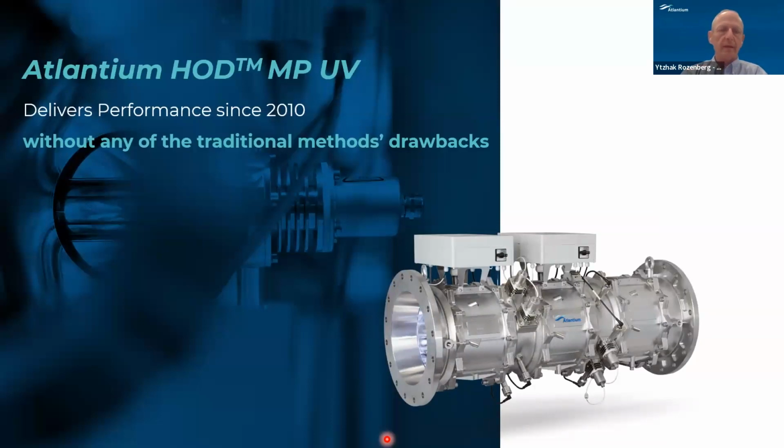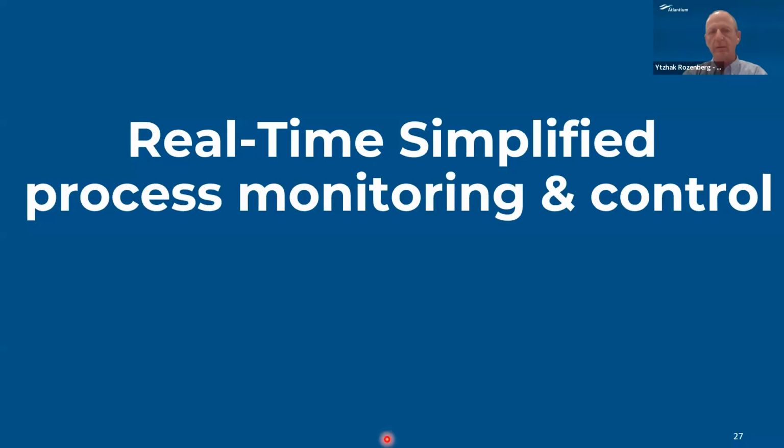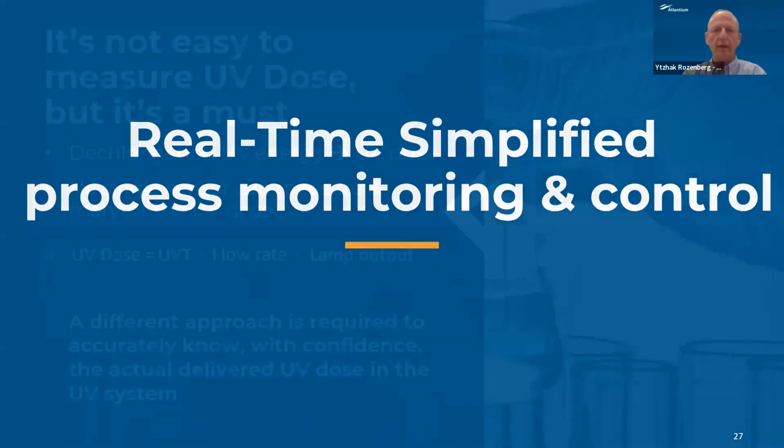We have installations since 2010, meaning each one of you that decides to use the UV for dechlorination for sure will not be the first one. It overcomes the traditional method drawbacks and protects your membrane from biofouling. We put here deliberately the big N because it's doing two in one. Real-time simplified process monitoring and control is very important for any treatment facility, for sure in the RO membrane when you are trying to avoid any oxidation of the RO membrane.